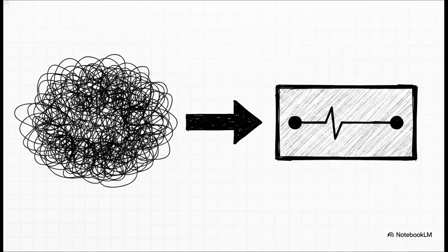This brings us to the ultimate modeling tool that engineers use to radically simplify what would otherwise be a total mathematical nightmare. Using the Thevenin's equivalent circuit approach, each complex sequence network is replaced by a simple equivalent circuit strung between just 2 points. Point 1 is the fault point, point 2 is a zero potential of the reference bus, labeled N. By doing this, an infinitely complex network is beautifully reduced down to just a single voltage and a single impedance inside a neat, calculable box.